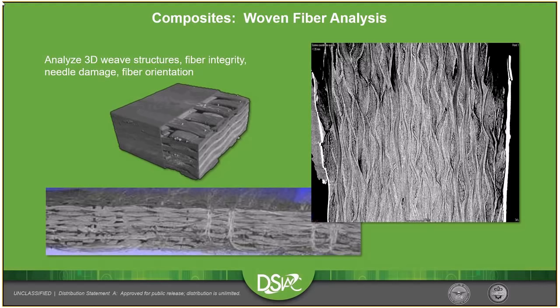We can virtually section out the outer layer and see inside of it and cross-section even more into that weave structure. Any way we want to, really, we can rotate that around just as a CAD model and strip away different sections, which can be very helpful in confirming a manufacturing process or identifying a defect or a weakness. And then that image on the right is aramid fiber, so you can see any delaminations in there as well, before and after it gets pressed into an armor mold.